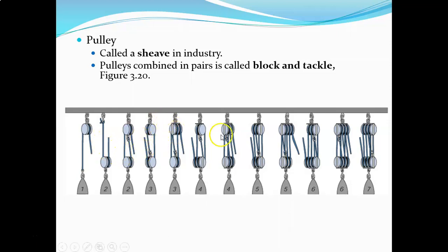So we move on to example 3. We're pulling down on this rope, and we still have just a mechanical advantage of 2, but what we have is 2 sheaves. We've got a fixed and a movable. If you count your ropes that are supporting the load, not your pull rope if you're pulling down, you've got rope number 1, rope number 2, and they are supporting the load.